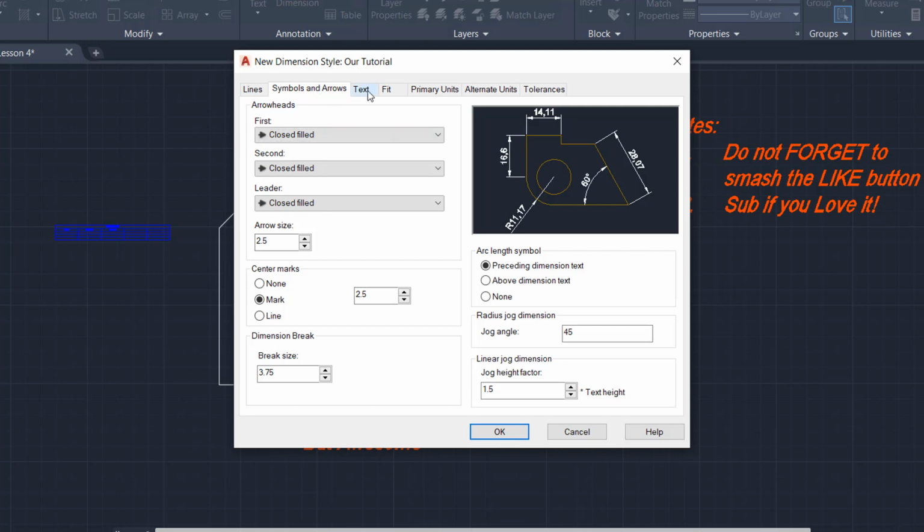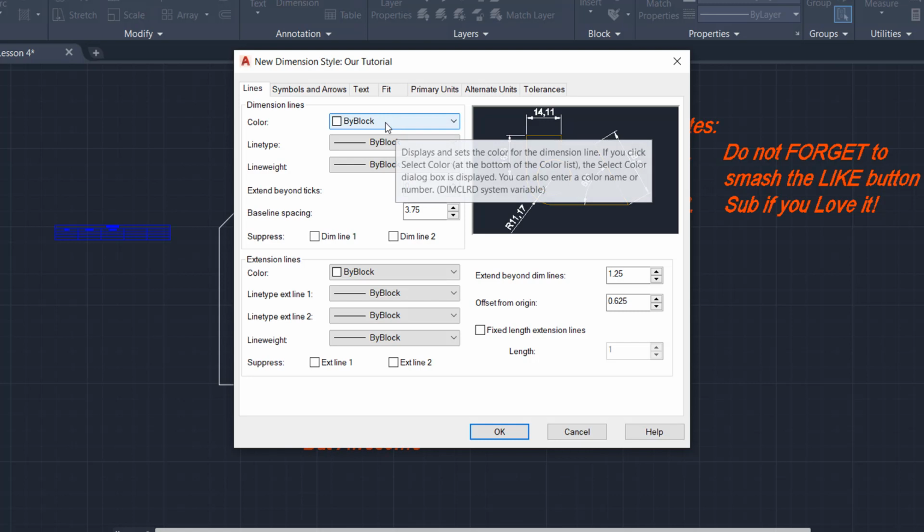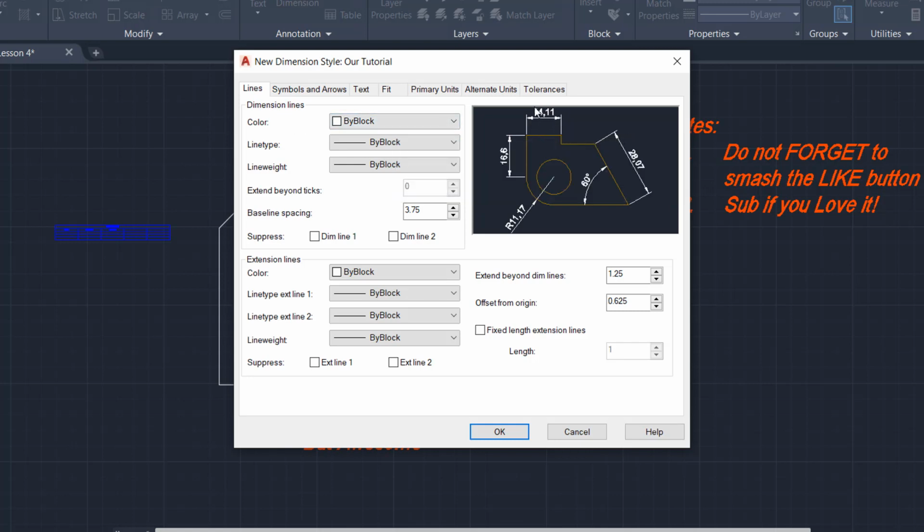Lines, symbols and arrows, text, and all the other settings. And again, keep in mind that everything will be in millimeters. Let's start dissecting. We jump into the lines. Dimension lines are these lines between the arrowheads. Make everything by layer. This way, it will assume properties of whichever layer is chosen. This way, it's much faster and easier. Always make a new layer for each thing. In this case, we will make a dimensions layer after exploring this. Baseline spacing is spacing between two dimensions, like in this picture.